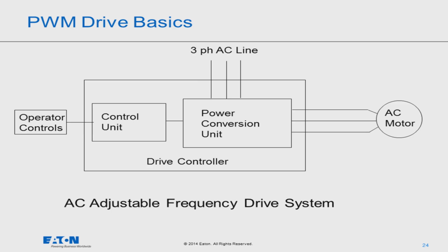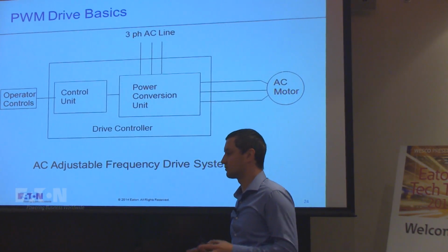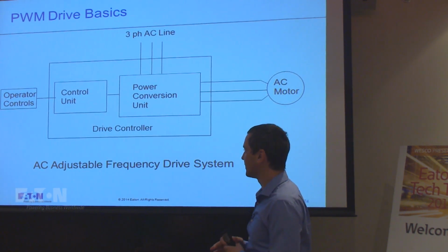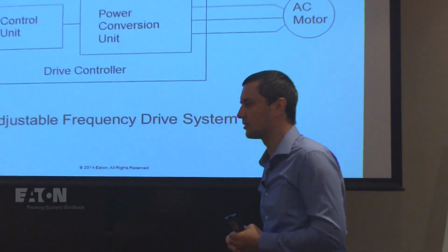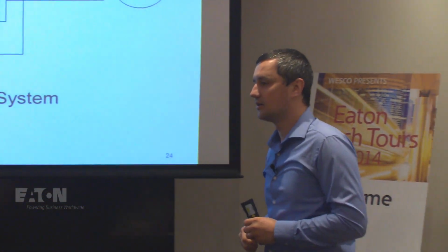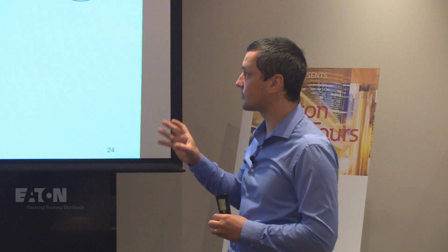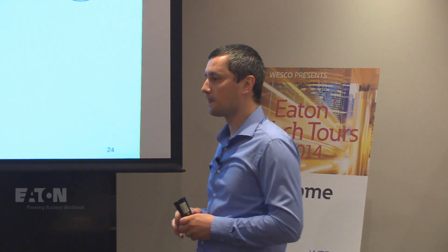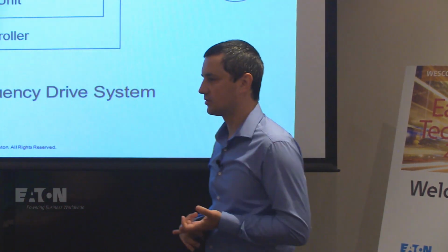Now, the drive. Drives are mainly built from a couple of main elements, okay? You have your operator controls, which can be, I don't know, your keypad, or an HMI through a communication or something like that. You have your control unit, you have your power conversion unit, and at the output, of course, you have your motor, okay? Most of the time with the drives, you have 3-phase in, 3-phase out, okay?